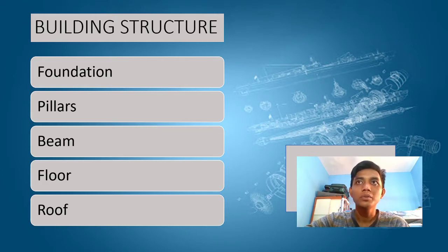The bottom of this pad is constructed at depth of 0.7 meter from ground level. This base measures 1.2 by 1.2 and then multiply by 0.4 meter.